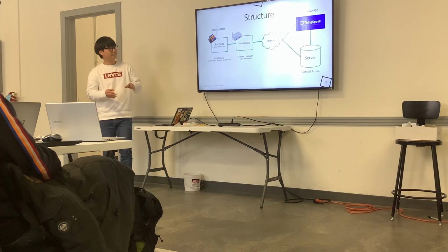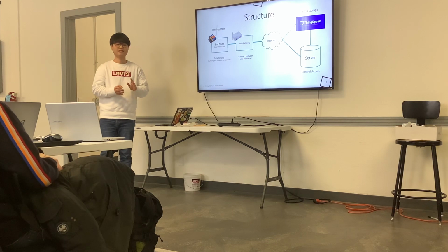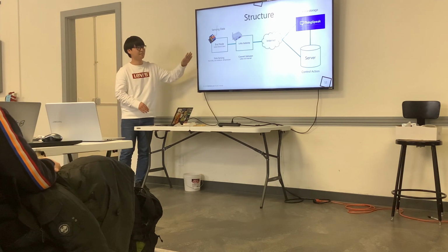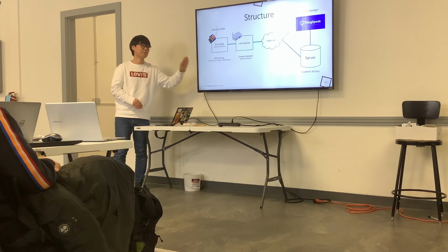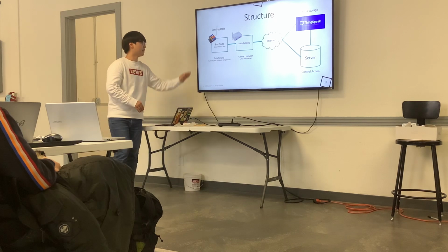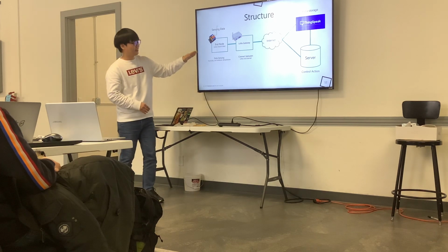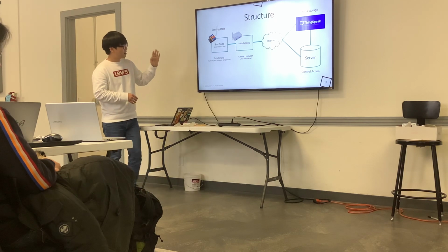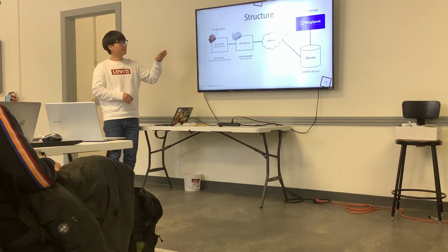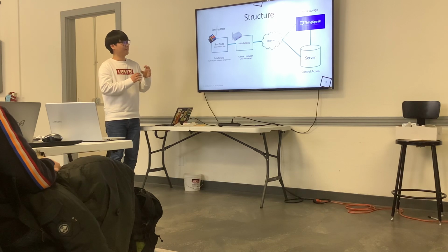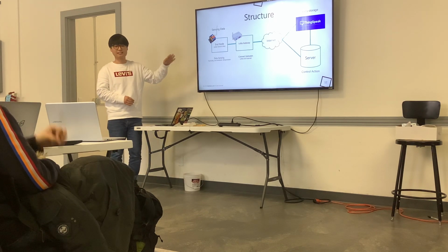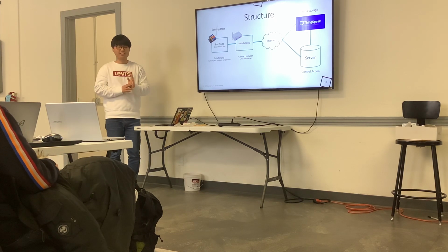So let's see how to gather the data. First, the end node checks the field's temperature, humidity, and soil moisture. Then the end node and the gateway are connected by using LoRa. The RadioHead library makes the connection wireless. Sensor data is sent every 20 seconds.